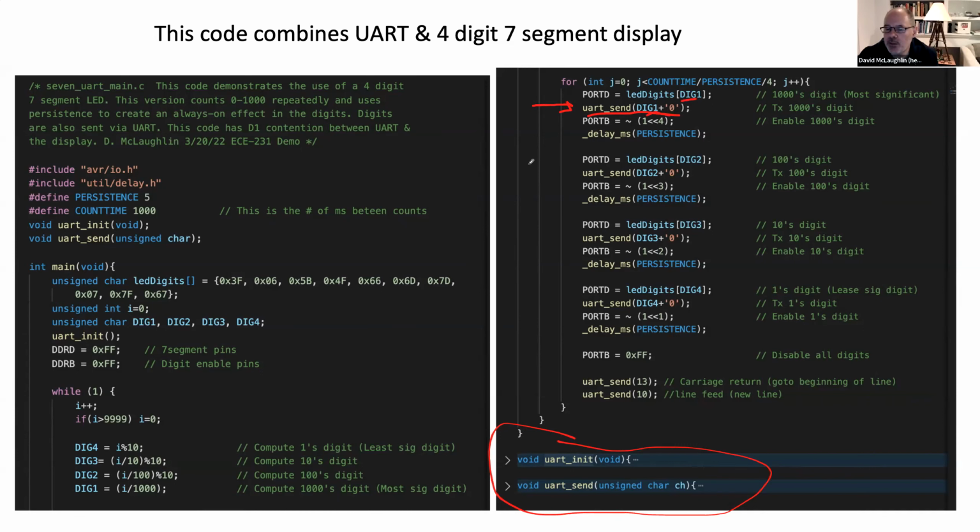This isn't necessarily the cleanest way to do it, but it works just fine. What I'm doing is I'm writing to port C, and then I'm also writing to port D. And I'm only pulling wires off of the upper 4 bits of one and the lower 4 bits of the other. And when I go ahead and do that, let me just show you 2 versions of the code. Okay, it starts running. Look for the 5. See, there's the 5, and we don't have that contention problem.